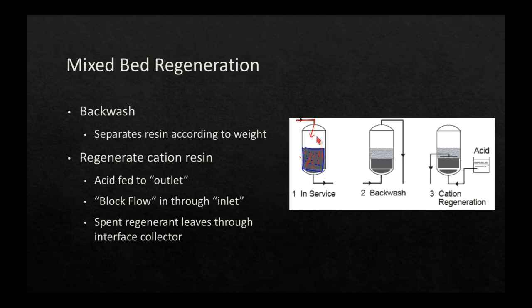So when the water flows through, basically what we're going to do is take this effluent from the demineralizer. And recall that the demineralizer is H2Z plus R.OH. Okay, so we're going to take that effluent from the demin, which is already demineralized, and we're going to give it a final polish. We're going to remove last traces of silica. We're going to make sure nothing has leaked through. We're going to give it that final polish. So in service, the water comes and it's in contact with both types of resin.